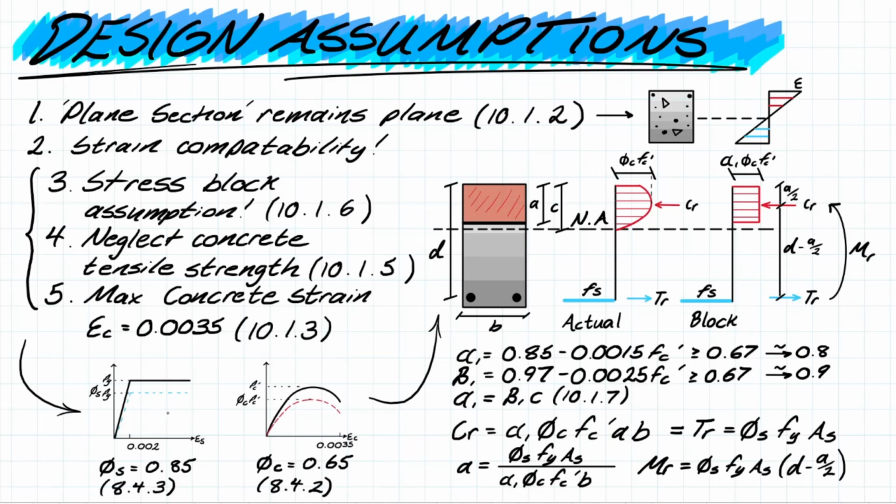You know, it doesn't have a mixed design that concrete would have, or a placing method where you're pouring, compacting, consolidating. There's a lot of other parameters at play when considering the strength of concrete. So we apply a factor that is lower than that compared to steel. But the main takeaway here is that we apply these factors in order to account for the uncertainty in the material once it is placed into our member.